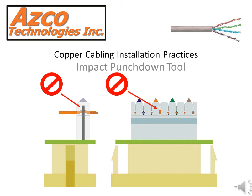Slide the individual wires down into the slots, and then using an impact punch-down tool, carefully seat the wires into the slots properly, making full contact.